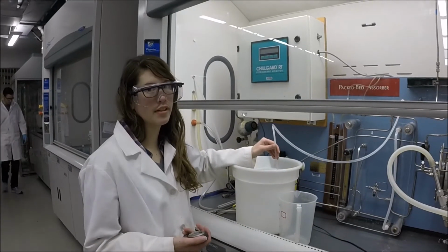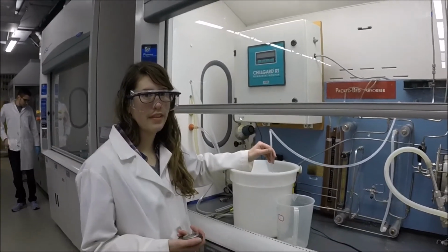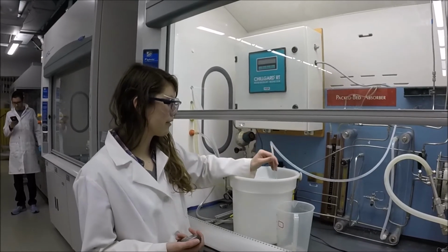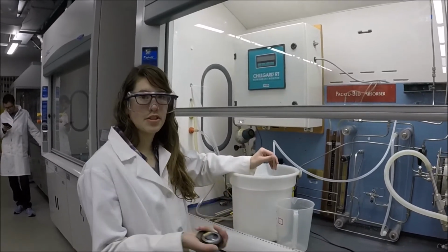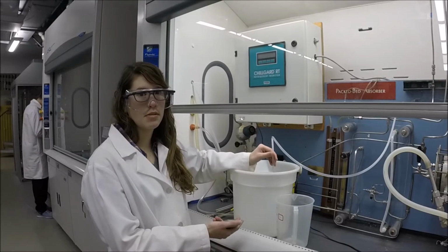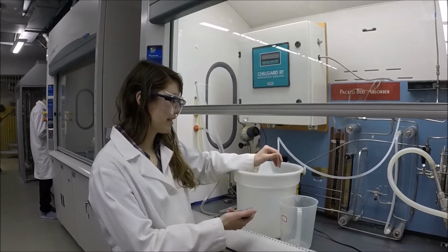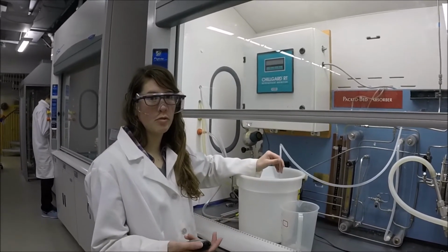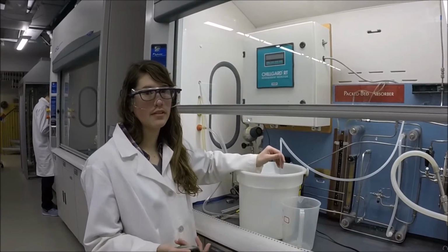To calibrate the flow meter, we'll use the bucket method. With the bucket method, I will take the water flow, let it fill up the bucket, and measure the time it takes. I will then look at the subsequent mass that filled the bucket, which has already been tared. This will give us a flow rate and will be repeated for subsequent rotameter values.